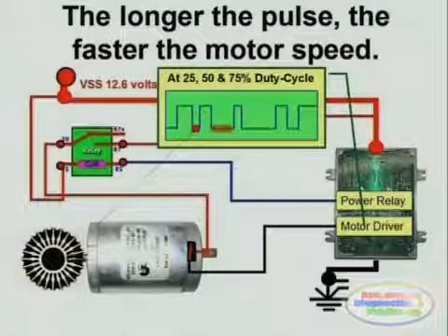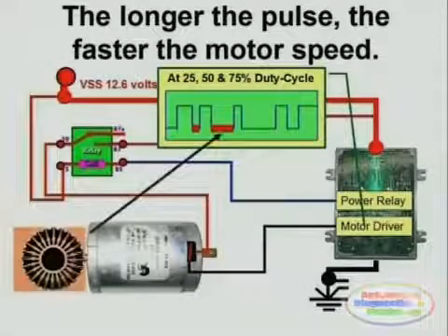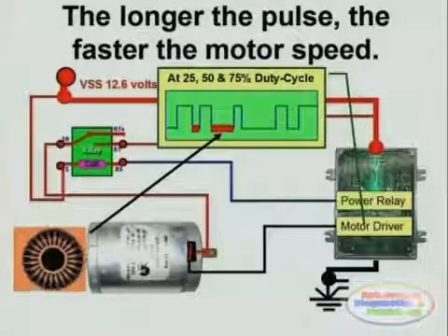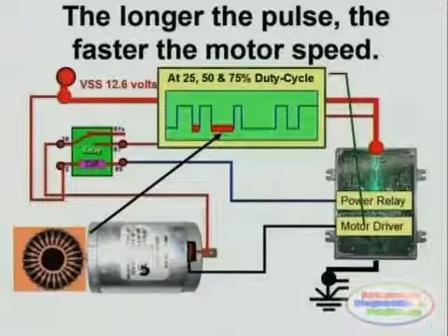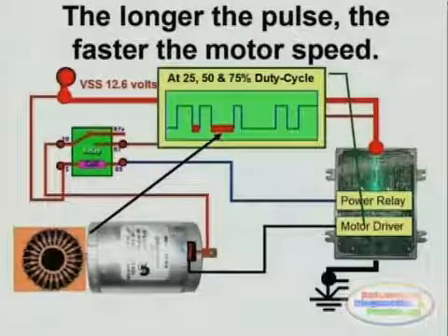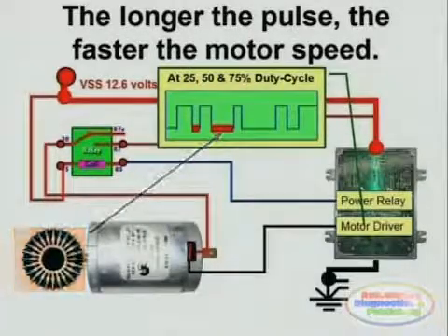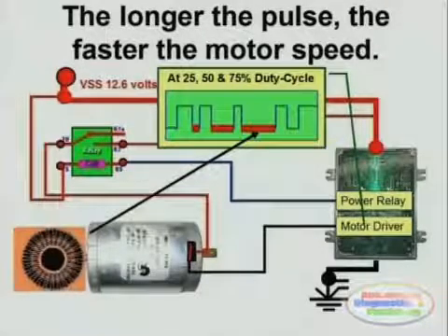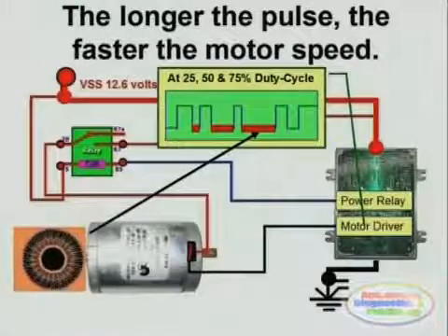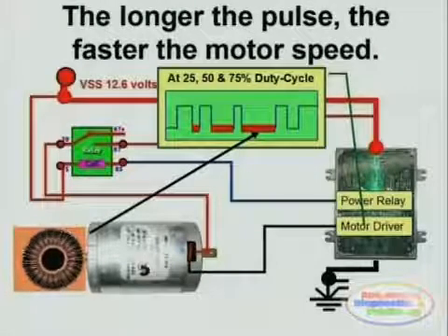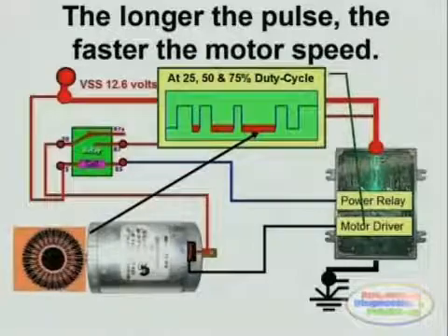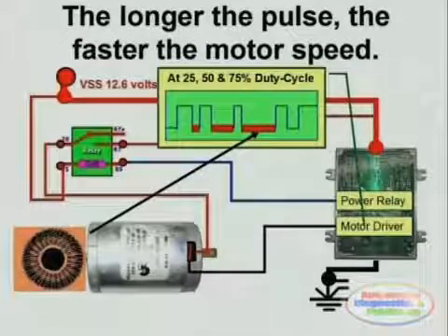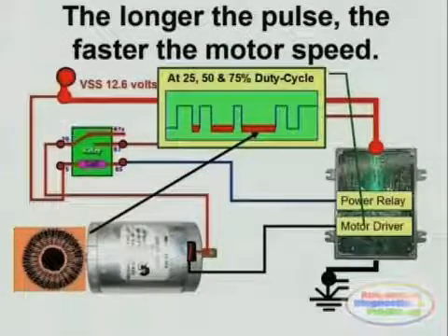At cruise speeds, for example, you will need maybe a 50 to 60% duty cycle for the fuel pump. And this we can see on the screen. And during extremely loaded conditions, as for example when towing, you will need maybe a 75 to 90% duty cycle, making the flow of fuel through the fuel rail a lot higher. You will need this type of arrangement in any system that is returnless.